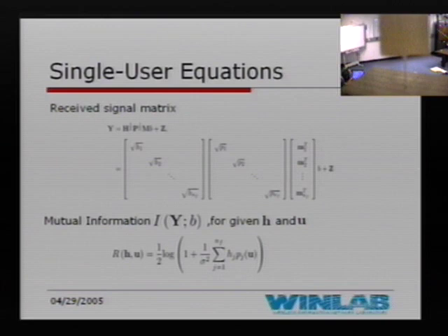Okay, so these are our transmission equations. We have a symbol B which is multiplied by a code matrix capital M, then by a diagonal power matrix capital P, and again by a diagonal channel matrix capital H. The rows of these matrices basically correspond to my NF subcarriers, and along each subcarrier I have the CDMA code. Excuse me, you multiply by the channel to the power of half? Basically, it's just a notation. Oh, that's just a notation. So you call your channel each one half. Yeah.